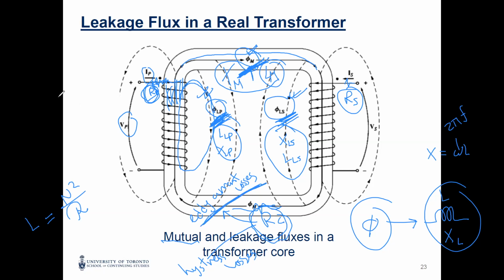Remember the eddy current losses: the core of the transformer is laminated, so they are small, but you still have some currents flowing inside the core. It's small, but still you have losses, so it's not zero. You also have losses because of your magnetic material. It's the hysteresis losses, a characteristic due to the BH curve, or hysteresis loop, of your material.